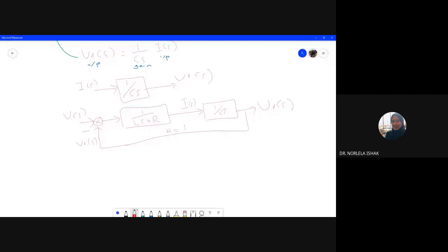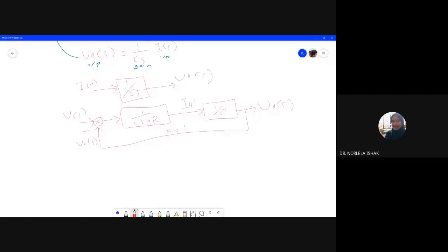From this sharing session, we derive the transfer function based on the block diagram reduction technique, so there is no need to substitute the equations into each other. To get the equation, you have to rearrange to get output equal to gain multiplied with the input. Once you get the equation, you draw the individual block diagrams, and then the next step, you get the complete block diagram.